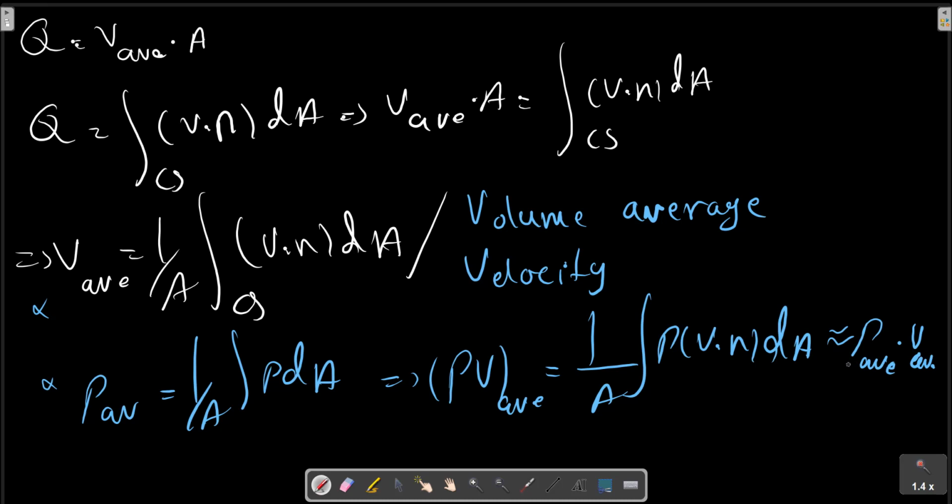Be aware that there is subjectivity in specifying incompressibility. Oceanographers consider a 1/10% density variation very significant, while aerodynamicists may neglect density variation in highly compressible, even hypersonic, gas flow. Your task is to justify the incompressible approximation when you make it.